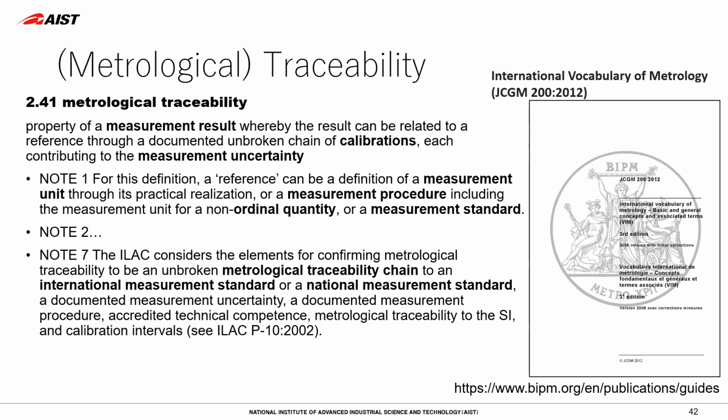Their standard instruments or artifacts are periodically shipped to a calibration laboratory at a higher level. Such a higher level laboratory claims a smaller uncertainty than the client. The same procedure is repeated, and at the end, the measured value and its uncertainty lead to the national standard. This hierarchy of calibration is called the calibration chain.